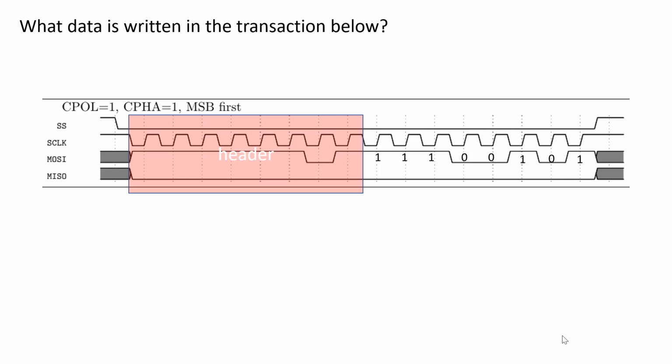I mean, you might be able to eyeball that and just kind of cut it in half, find the second half, but I'm not that good. So I'm looking at rising edges here, right? So I'm counting 8 rising edges. And then the second 8 rising edges will correspond to the data, which is 1, 1, 1, 0, 0, 1, 0, 1. Right. Okay, any questions?